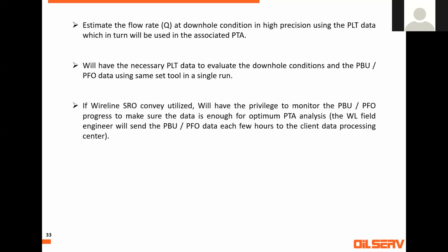They pass the wellbore storage, they pass the wellbore effect, and they enter the reservoir area. When they have sufficient data to make a robust PTA analysis, they will ask the engineer to stop. They will not have this privilege with a memory tool.